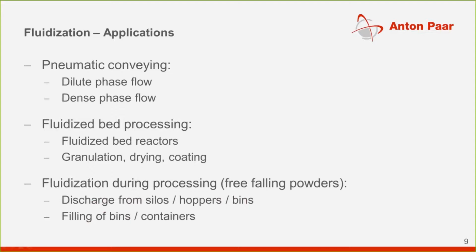This can result in uncontrollable discharge, and it's something we'd rather be sure to know about. What might change as well, and what is interesting when looking at the filling of bins and containers, is that the bulk density might change drastically as the sample takes in air and retains the air for a certain time. So this might also negatively influence downstream processing of the powders.